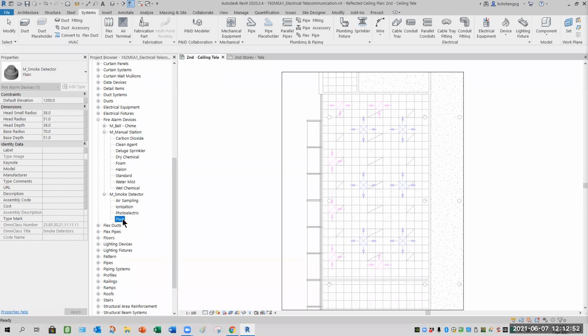The ionization is like a smoke alarm detector, detecting the smoke. The most common should be photoelectric, because when you dispose of the ionization type, there is nuclear waste. It's hard to dispose. I see. So normally they use photoelectric, for common use.